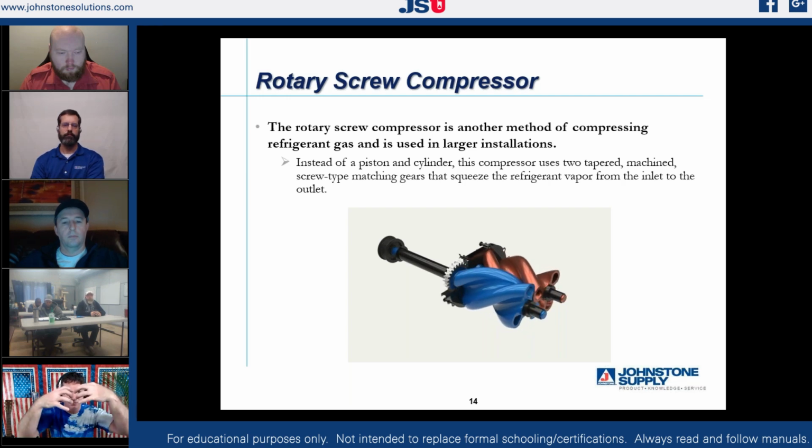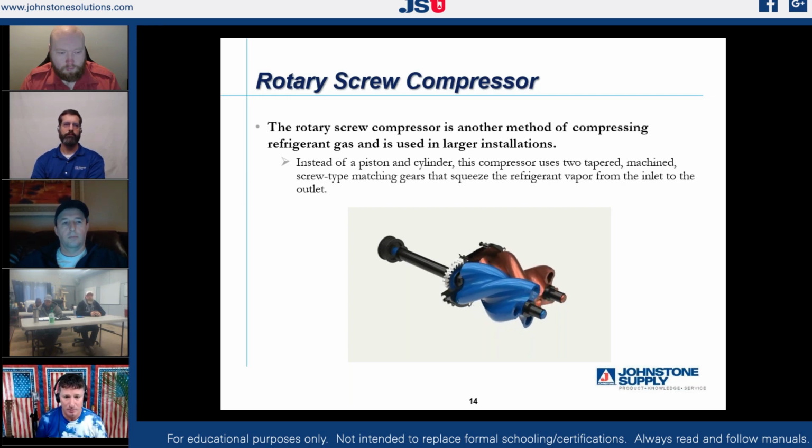It is an inner vane vapor pump, and that's all that it is. So even though this thing could be the size of this room I'm sitting in, it's just a big vapor pump being driven by an electric motor typically. On larger applications, say a cruise ship using a rotary screw compressor for its air conditioning refrigeration system, what's it being driven by? A great big monster diesel engine. Same thing. The locomotive force we use to drive our pumps can be different, but our pumps are just pumps.